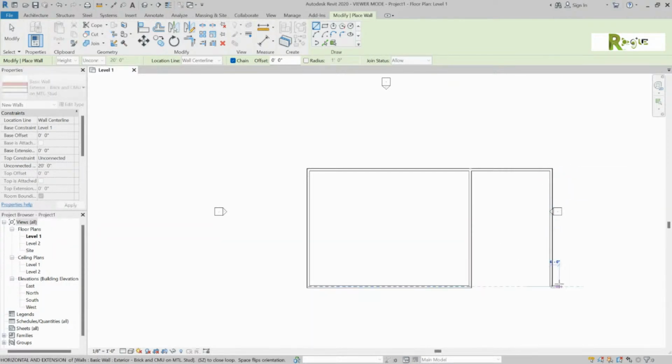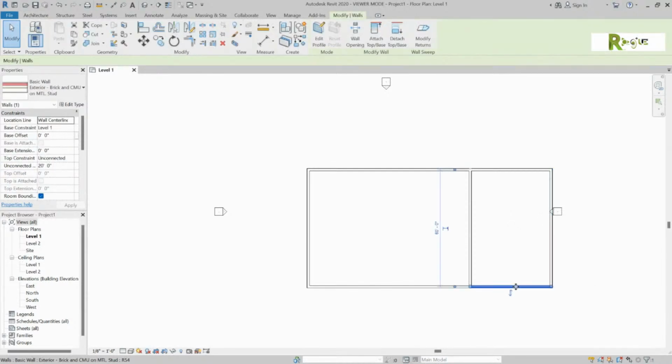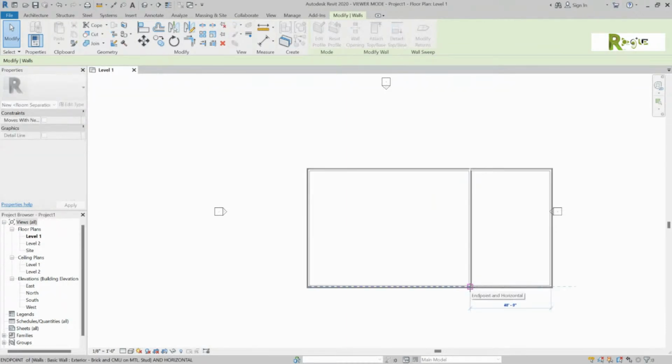Nope. Don't do it the full length. Where's the undo at? Nope. Don't go to undo. Just draw the wall, but don't connect it. No, don't connect it. That's all right. Now escape 2 times. Escape 2 times to get out of the command. Okay, that's going to be real important. Now pick that short last wall you drew. The short one. Grab that little blue dot at the end of it. Other end. And pull it away.